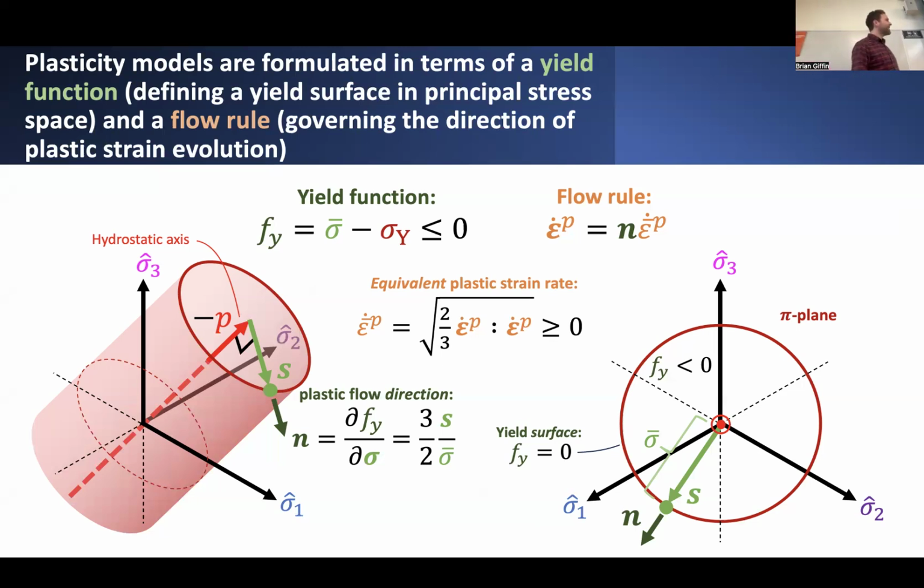characterizing just the shearing part of the total stress. And we determined that if we wanted to come up with some criterion for plastic strain evolution, really based on experimental evidence and other kinds of material science principles, we rationalized that, especially for materials like metals and things like that, it's really only the shearing stress, the deviatoric stress, which influences plastic strain evolution, and which is also governed by some constraint on the maximum stress prior to which yielding occurs.